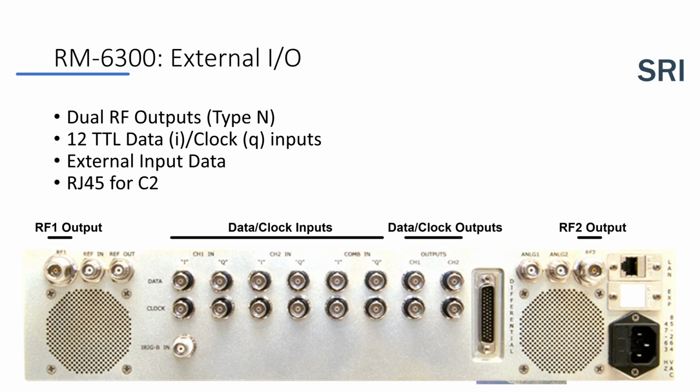The TTL data clock inputs offer unmatched configuration options here. So, 12 BNC female connectors for TTL data clock inputs. This is how we stand out from the competition, with the capacity to accommodate a wide array of data and clock signals, enhancing the device's ability to simulate complex digital signal environments accurately.